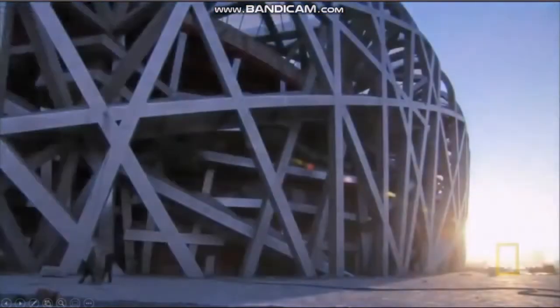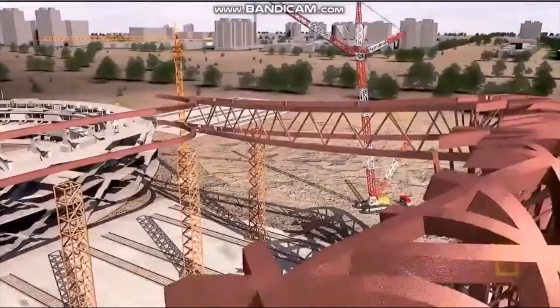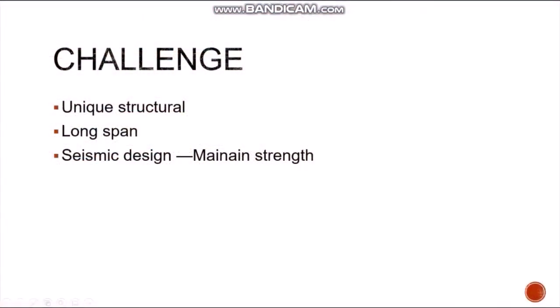The long span also causes the strain capacity of the primary truss members to be taken up primarily by gravity loads. The box section top chord and the diagonal members in the primary trusses are subject to high axial compression forces under gravity loads, and will sustain damage and degrade in strength due to global as well as local buckling.